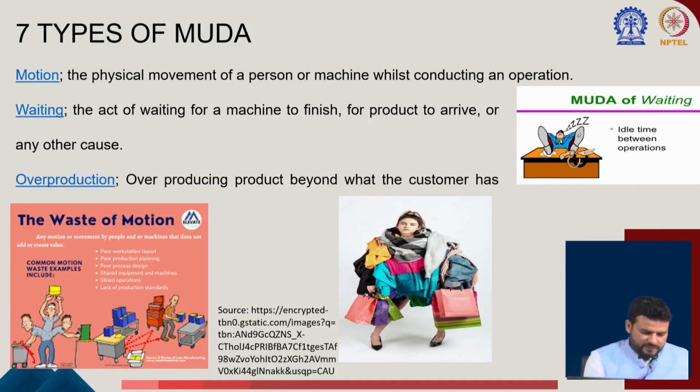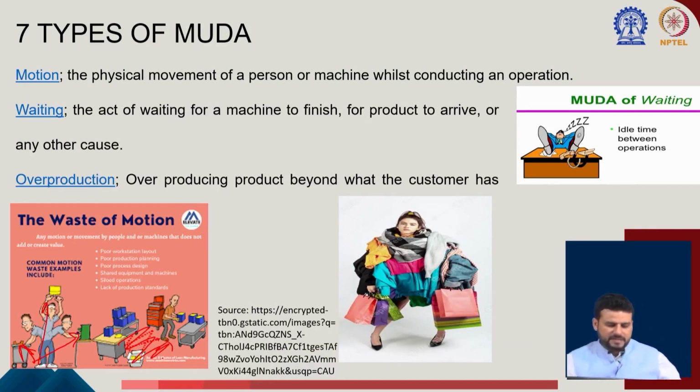Now this person is moving sometimes to this bin, sometimes to the workstation, sometimes carrying the product, so there is zigzag motion. While moving he is wasting time, which is extra motion, extra waste. This person is waiting for the call, and only then will he respond, so that is waste. How can you ensure a smooth channel, so that every workstation has some work to do?